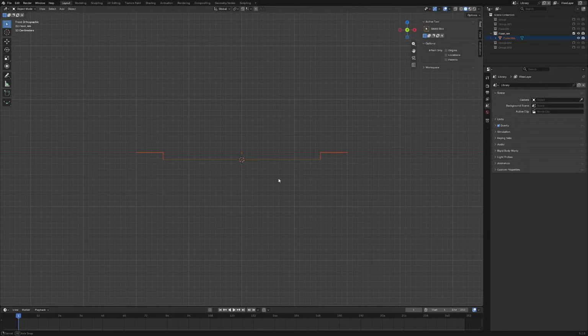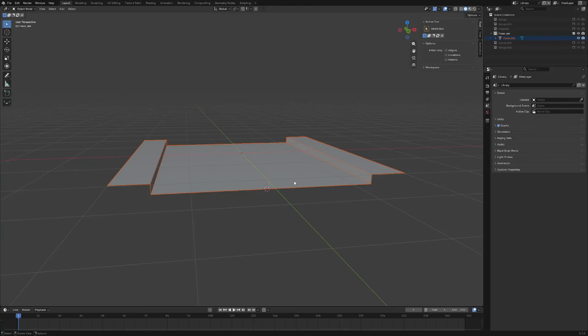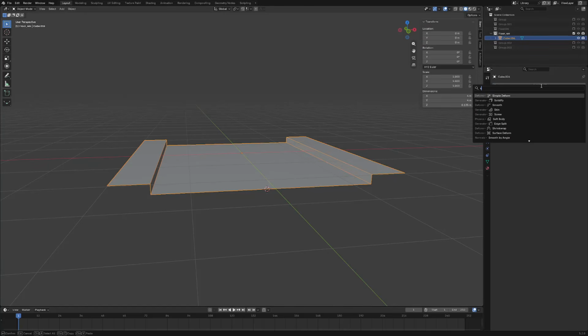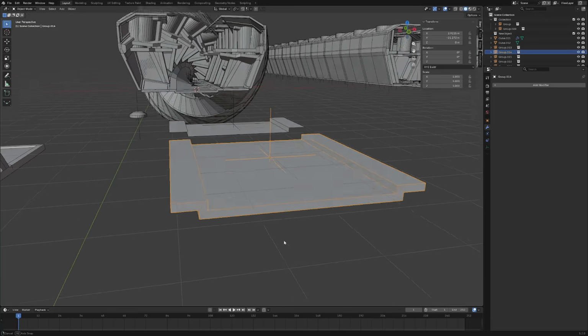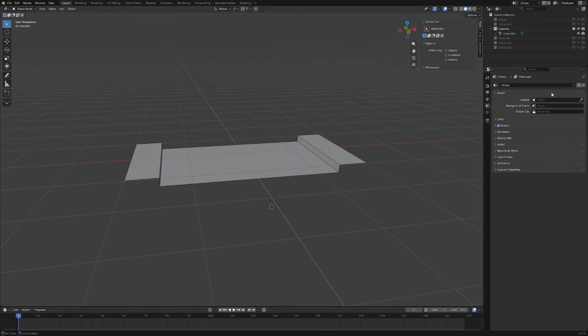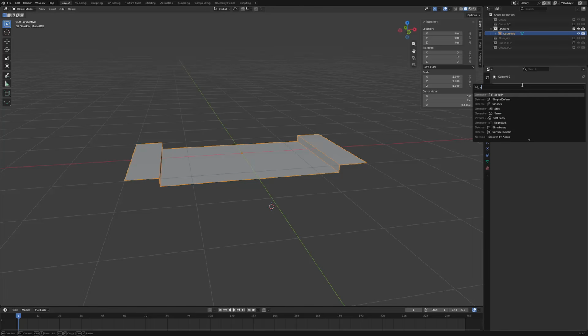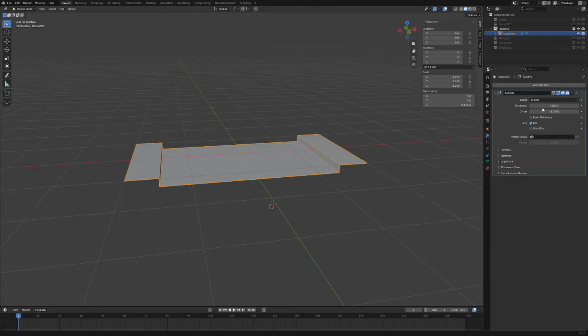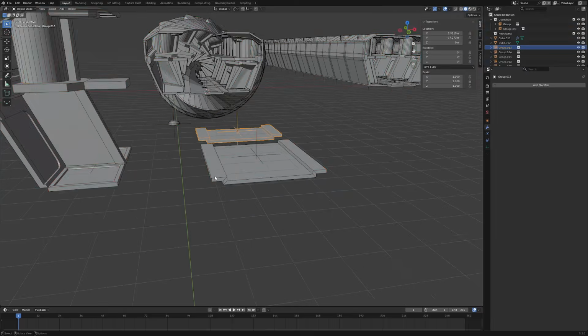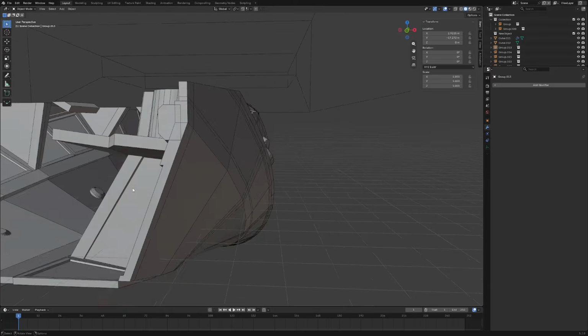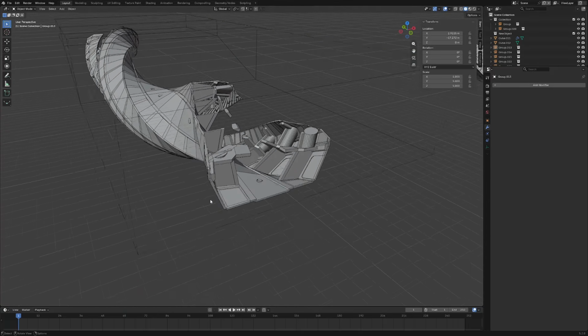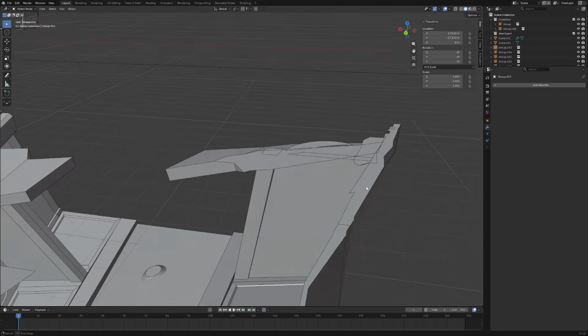Let's just come over here real quick, and I'm going to add a solidify modifier to this, actually. We'll keep it simple. We'll just solidify it out. And maybe even thickness. All right, Tab back out of that one. We can get into this one, Tab in, grab it, solidify. It has to be solid. That's why it's called manifold solid. You can't just leave it open-ended like that. I don't think I did anything else open-ended, so it should be working now, hopefully. There you go. And yes, it can create a mess too, just like any other Boolean.